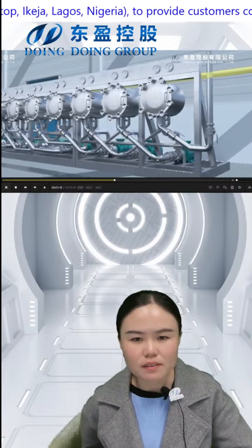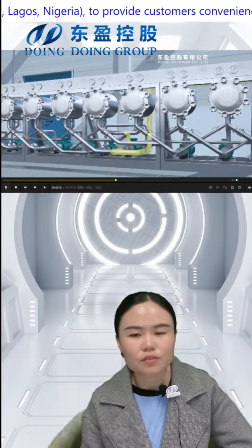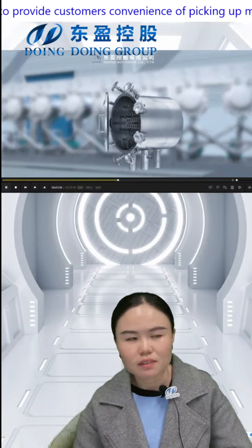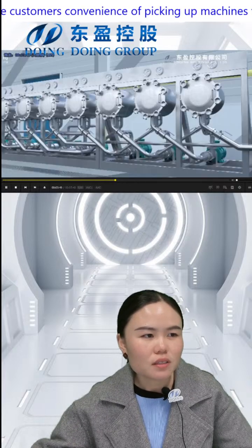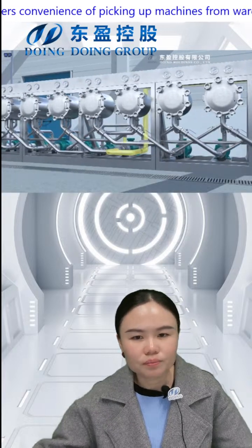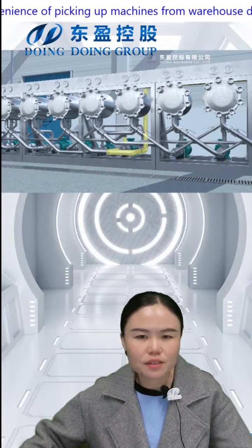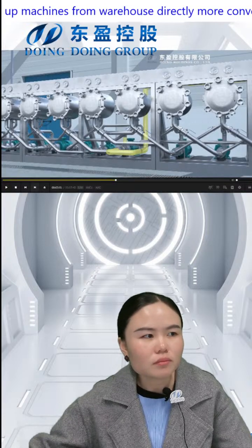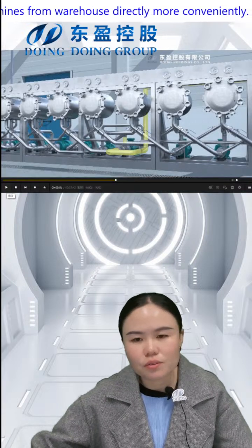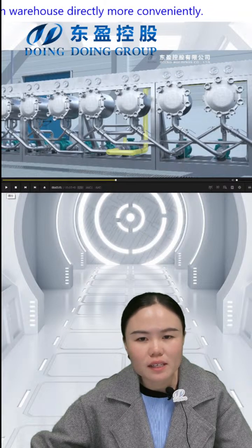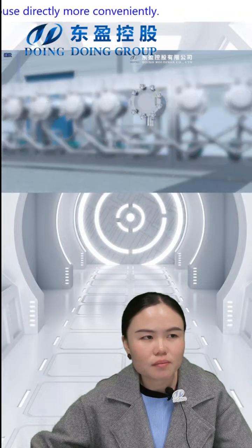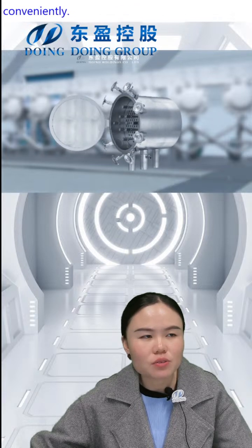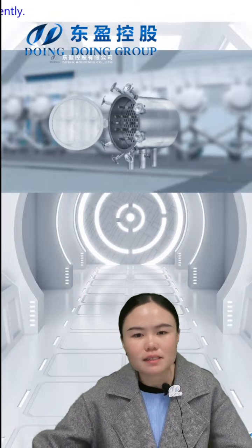And after the desander, this slurry will be pumped into this hydrocyclone machine. This hydrocyclone machine is used for protein and cell liquid separation, and to ensure good working efficiency, 18 stages are matched. This hydrocyclone machine, this is how it looks inside. We can see the inner structure.